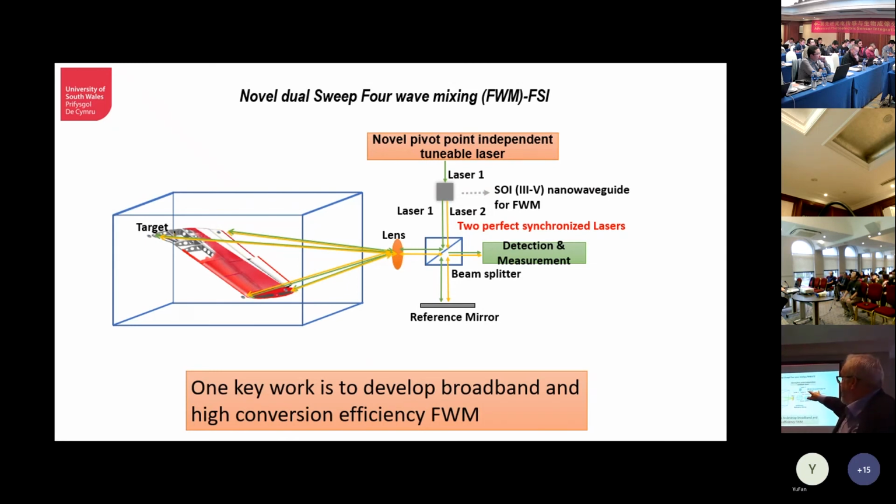There's an example here. We've got the wing in the factory. You can see we've got multiple targets. Remember, this technique can measure more than one target at any one time. You've got your beam splitter, and you basically just throw the light into space. And then you've got these targets, these small ball lenses, refracting and reflecting light back in. And then you've got the detection system.